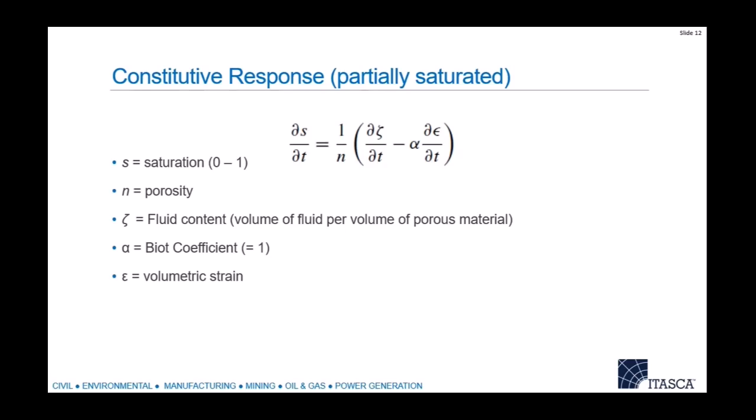Again, pressure increases with more water, and pressure decreases with expansion. If you're unsaturated, S here represents the saturation. It's always a value between 0 and 1. If you're at 1, you're fully saturated and you're generating pore pressure. If you're between 0 and 1, the pore pressure is 0, or more properly, whatever you set as the fluid tension, because you can set it to whatever you want. You can set the fluid tension to -1e3, and then things want to saturate. The pore pressure becomes that negative. Most of the time, you're at 0.